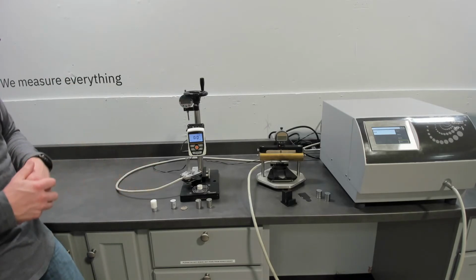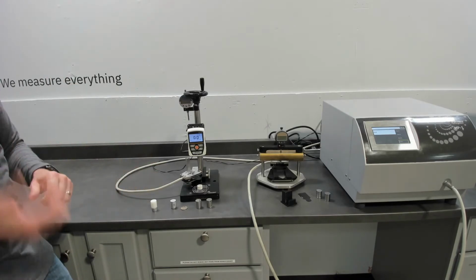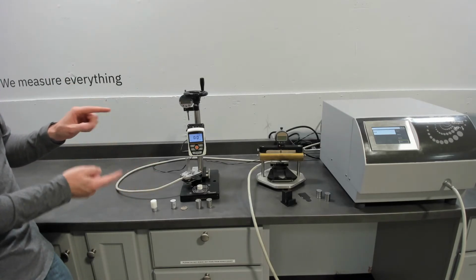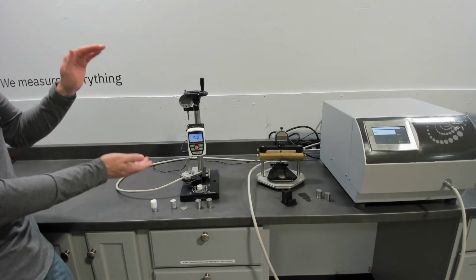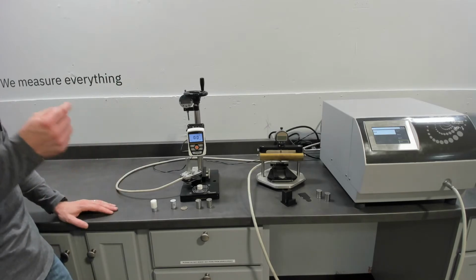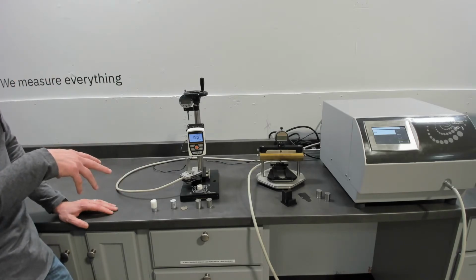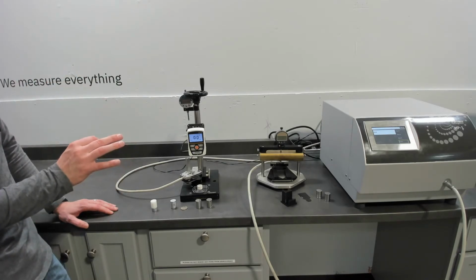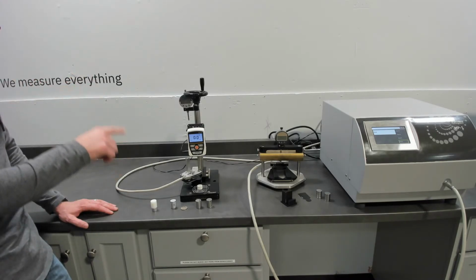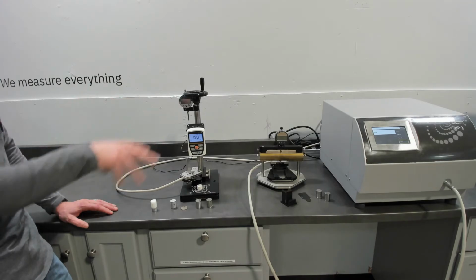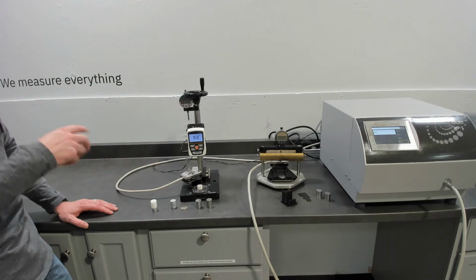So let's say you have an application and you're looking at an adhesive or a film and you want to introduce it between 2 specific types of materials with specific finishes with a certain pressure or temperature. You can see its true performance in that application versus its intrinsic thermal conductivity, which most likely is different than the applied thermal resistance due to those same variables that are introduced from the application.